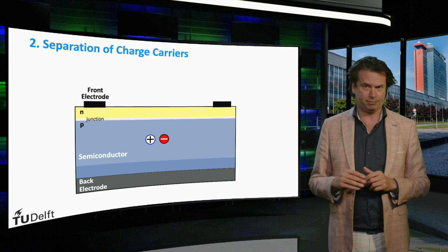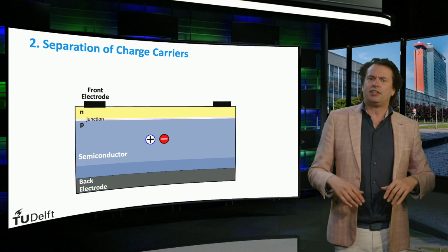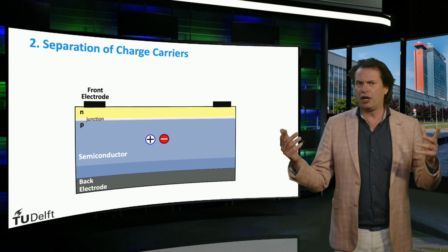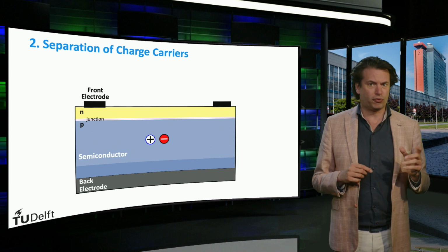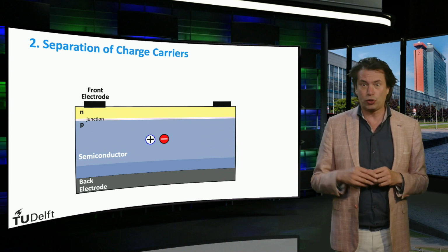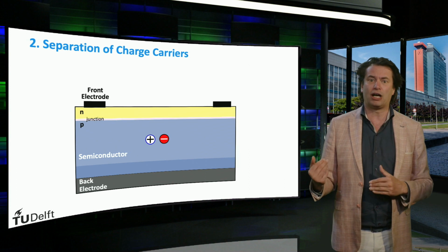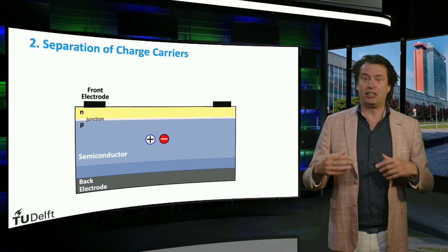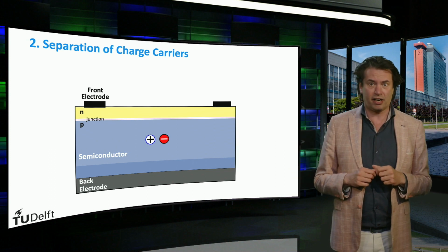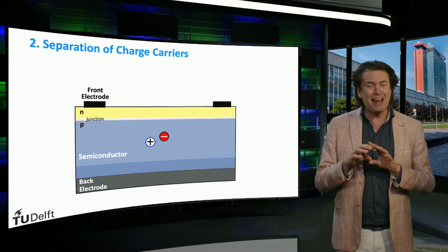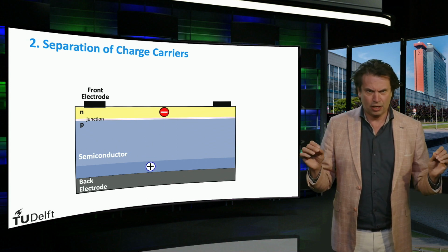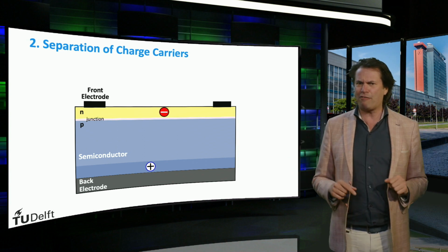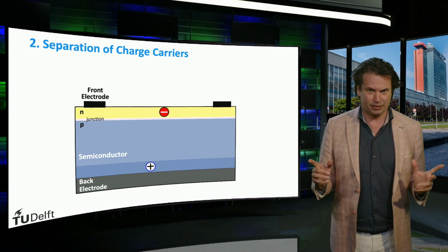through the other membrane. In our solar cell here, the charges were generated in the p-type semiconductor. As you will learn in later videos, the p-n junction at the top of the solar cell only allows electrons to pass through and the junction at the bottom of the cell only allows holes to pass through. Therefore, the solar cell needs to be designed so that the mobile charge carriers eventually hit those barriers and are separated. So now we have generated and separated charge carriers, but we have one more step to generate electricity.